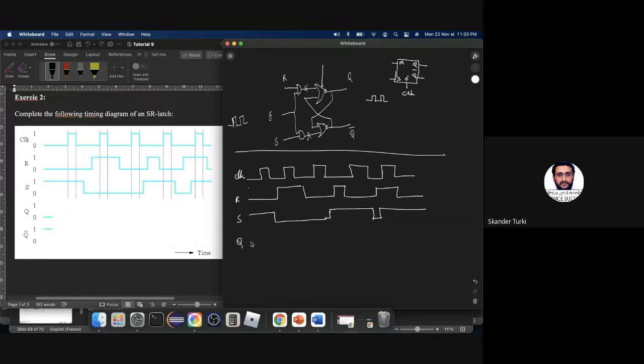So Q is 0 in the beginning. Okay, so what happens when the clock ticks here? Before the tick of the clock here, the system is like sleeping, and it doesn't receive anything. Of course, when the clock becomes 1 here, the system can react to the inputs. So it has an AND. So the 1 from the clock doesn't have an effect by itself. It needs either R or S, so that we have a 1 outgoing here or here. Okay. Is it clear or not?